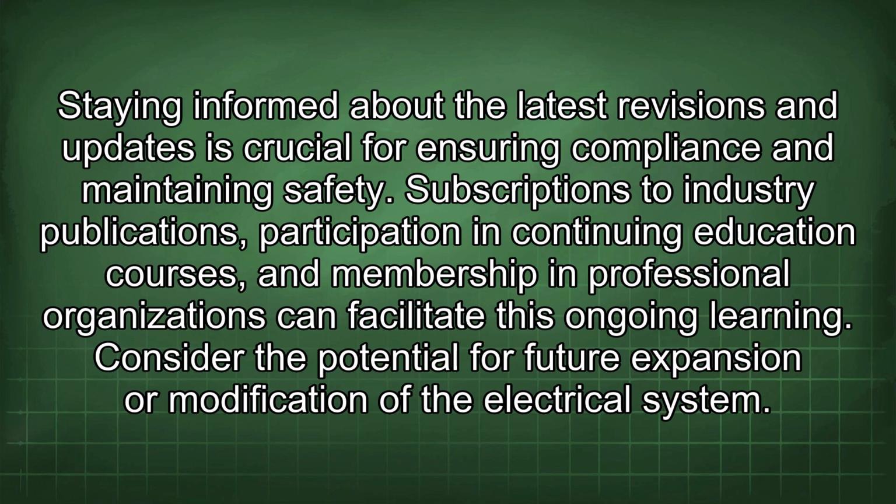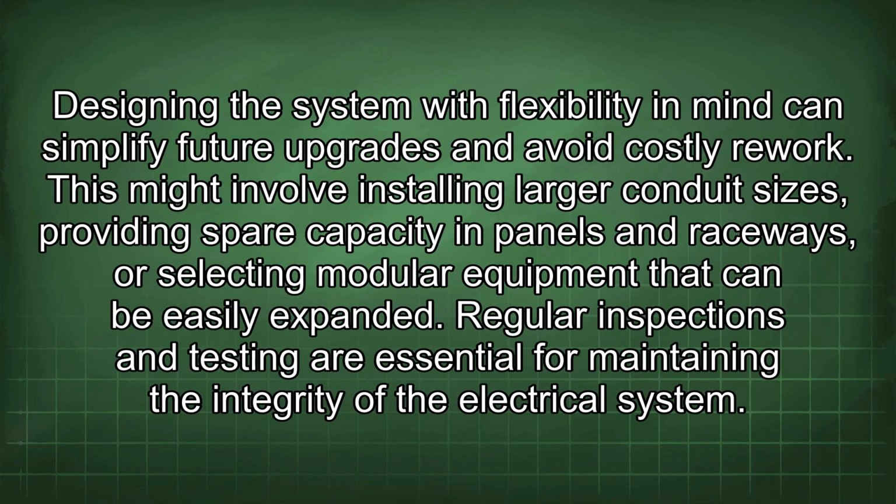Consider the potential for future expansion or modification of the electrical system. Designing the system with flexibility in mind can simplify future upgrades and avoid costly rework. This might involve installing larger conduit sizes, providing spare capacity in panels and raceways, or selecting modular equipment that can be easily expanded. Regular inspections and testing are essential for maintaining the integrity of the electrical system.